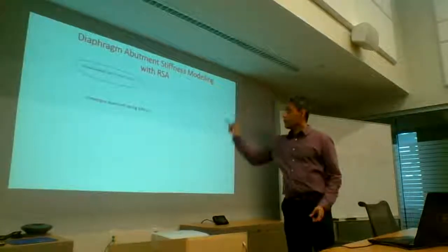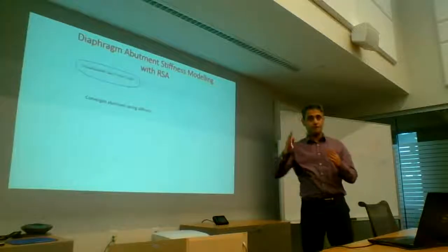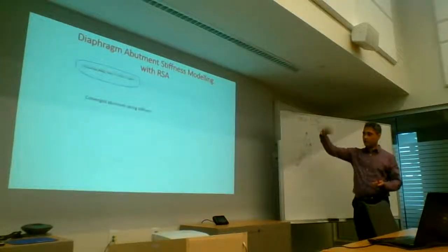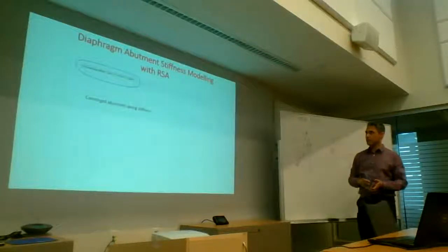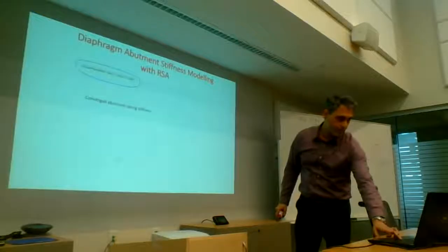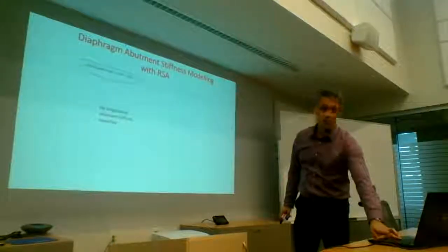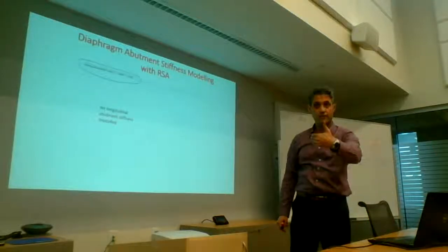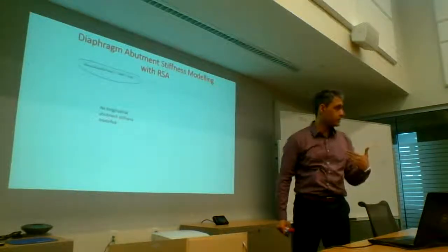But what I found with that was that the force that that spring was getting was way up there. So I'm not showing the intermediate iterations, but once it's converged, the period is 1.97. We started at 2.6. So there is a considerable drop in your period, which means you have a considerable drop in your displacement as well.